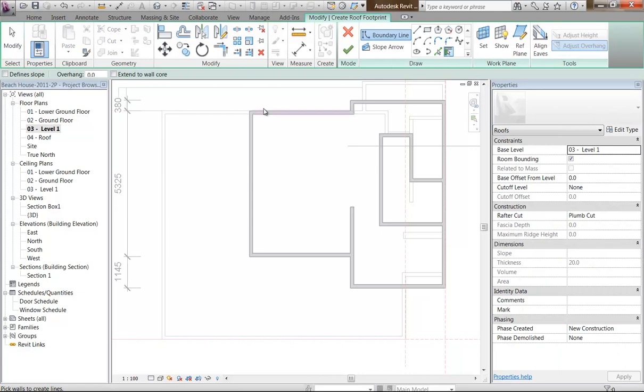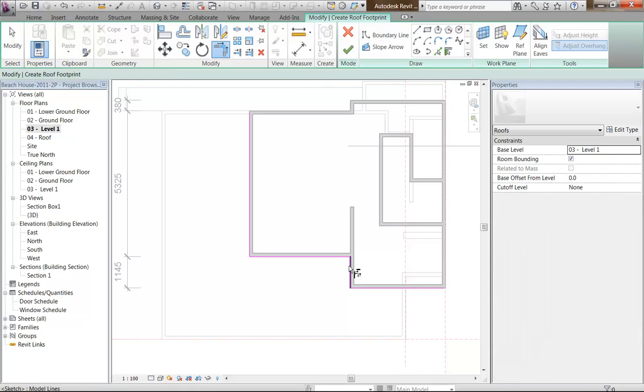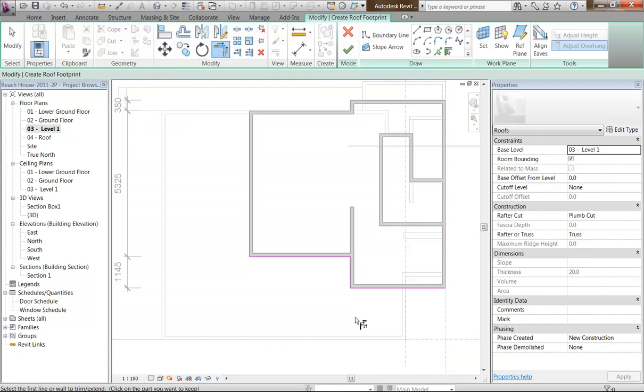to begin with, I can just pick edges of those walls because I know I want to stop there. So the edge of the roof is going to sit right on those walls, and I can use Trim and get that done without having to think too much about it. But then you've got the section of roof that goes over the walls. Now, it does extend out beyond the balcony, but then on the other side, it's got, I think, a very small eave. Again, I'm going to check that, but for now, I'll just do it with a little eave.